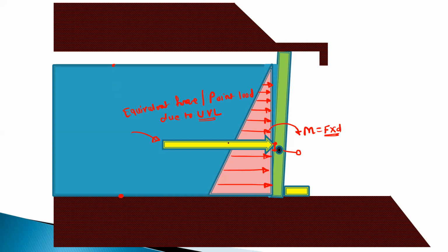Okay. So at the topmost point, which is in contact with the atmosphere or the free surface, pressure is zero because of the water. Okay. And at the bottommost point, pressure is maximum. So generally it is represented as rho g h. So h means what? It is the depth.